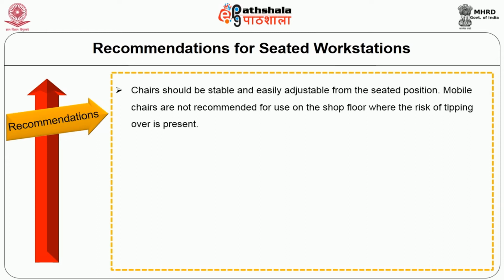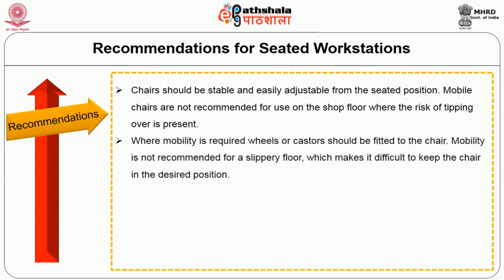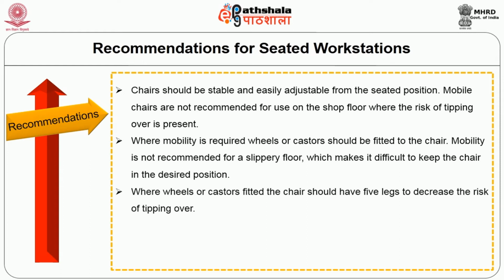Chairs should be stable and easily adjustable from the seated position. Mobile chairs are not recommended for use on the shop floor where risk of tipping over is present. Where mobility is required, wheels or casters should be fitted to the chair. Mobility is not recommended again for a slippery floor, which makes it difficult to keep the chair in the desired position. Chairs fitted with wheels or casters should have 5 legs to decrease the risk of tipping over.